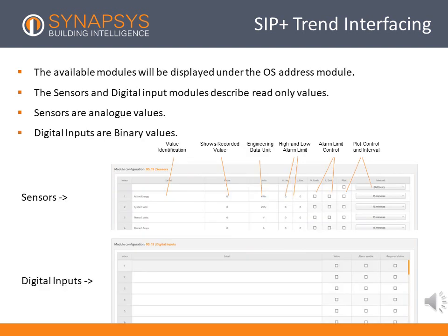When configuring the required modules, ensure labels, units, high and low limits, and plot information is entered where they are needed. The copy and paste function allows this information to be copied out in a CSV format and edited in an Excel document. The table can then be pasted back into any other created outstation. You can also right-click an outstation to duplicate it.